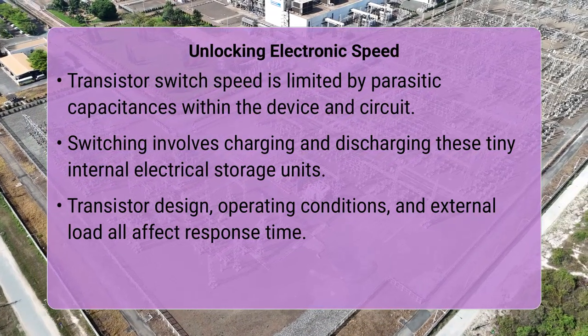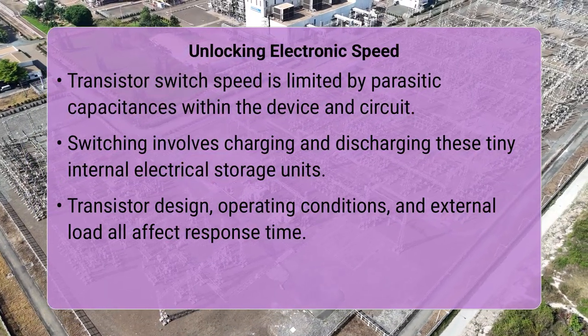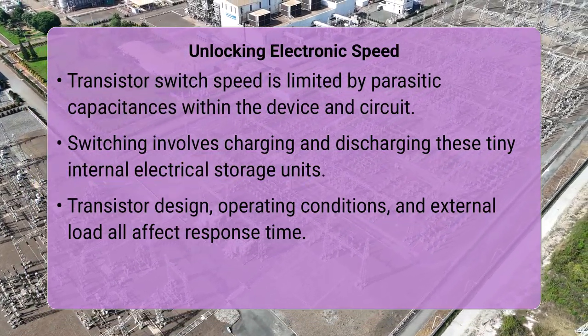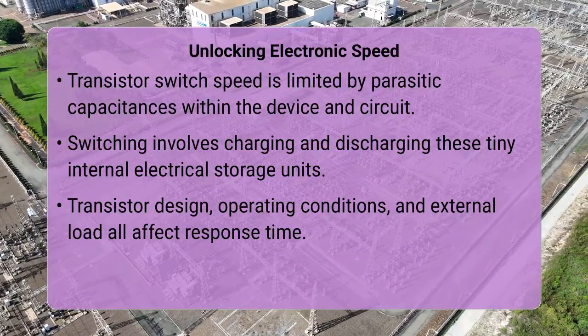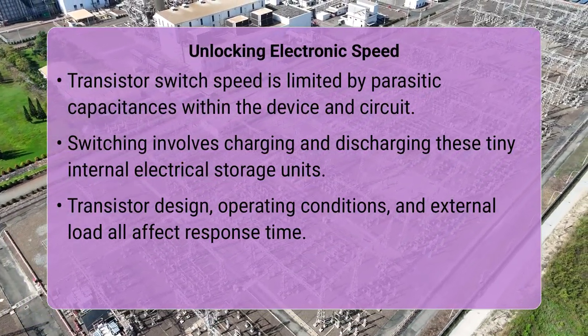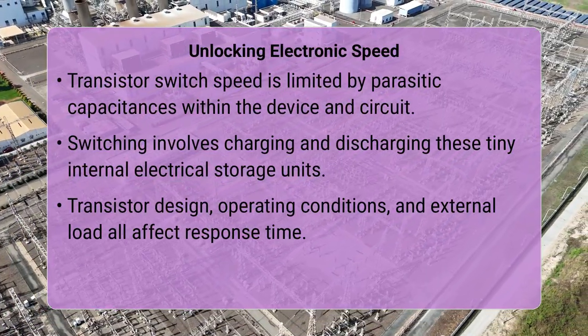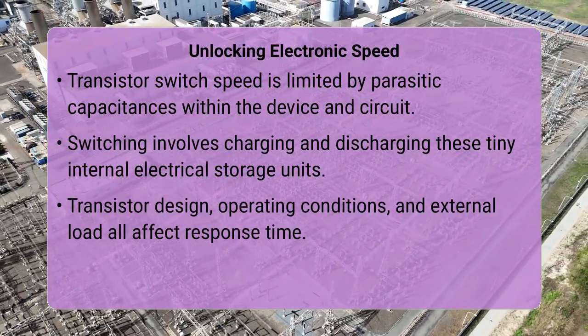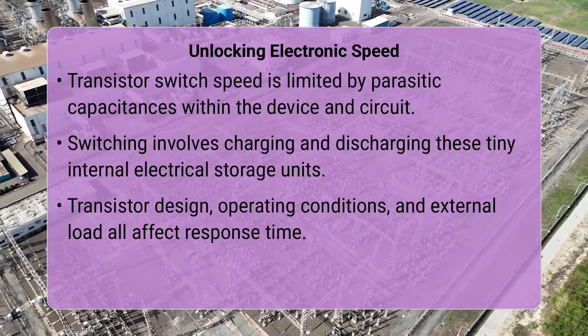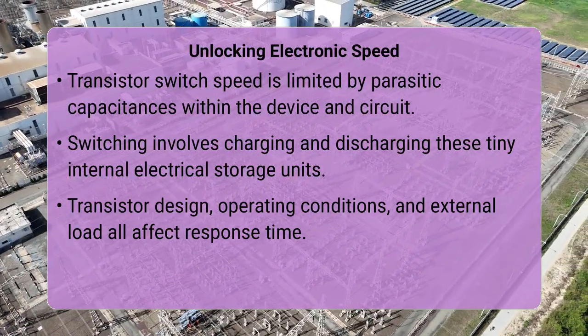Have you ever considered what allows our electronics to perform complex calculations and operations at such incredible speeds? Transistor switch response time is primarily determined by the time it takes to charge and discharge parasitic capacitances within the transistor itself and its immediate circuit environment.